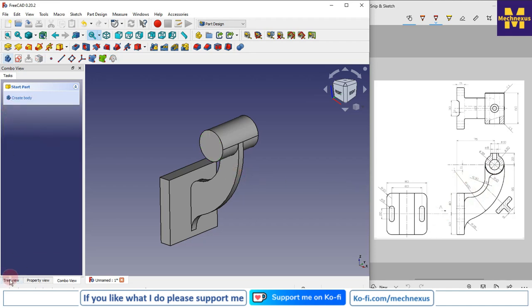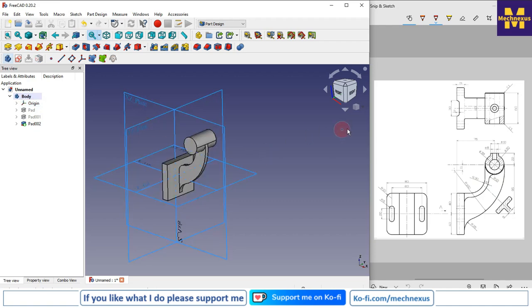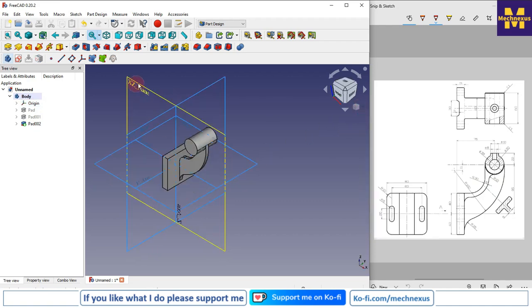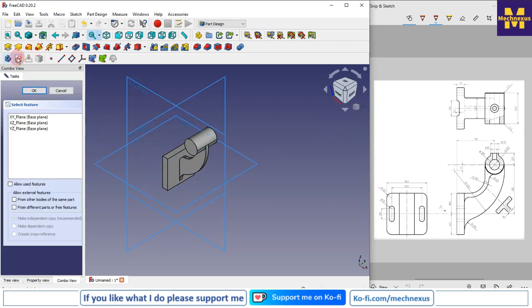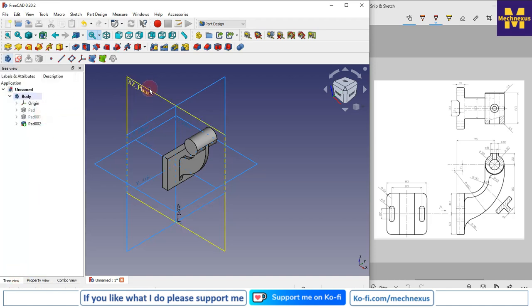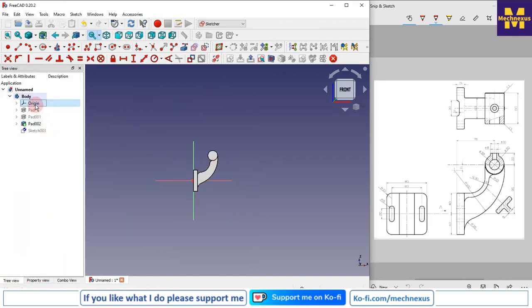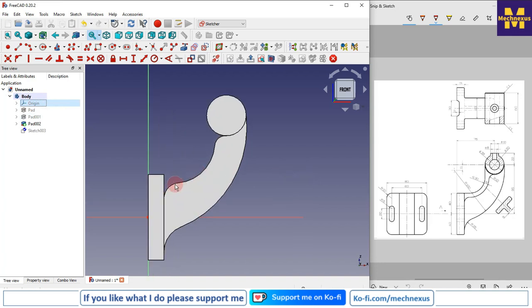So for this we again select a mid plane. We will turn on our origin plane and select this XY plane and create a sketch. Then we'll turn it off. Now we will project this edge. Click on convert project geometry. Now I will project all this. For better visibility I will switch to the wireframe,